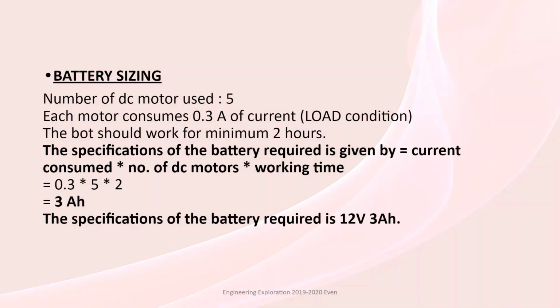Battery sizing. The battery sizing depends on the total number of DC motors used, the current consumed by each motor, and the working time of the bot. By calculating all these, we obtain the specification of the battery as 12 volt 3 ampere hour.